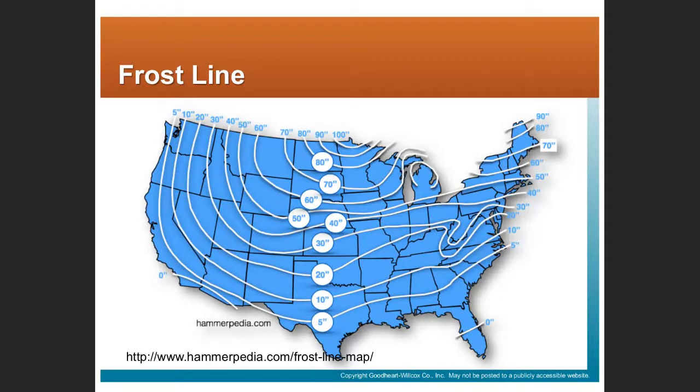So I would say if you're building a residential site, you probably know based on the general location you're building and what the soil conditions are. If you're building a commercial building, you're generally going to do some kind of soil testing to know exactly the conditions of the soil, and that soil testing results will be given to the structural engineer or the civil engineer who's doing the foundation design to make sure that they design the foundations or footings or columns or pilings accordingly.